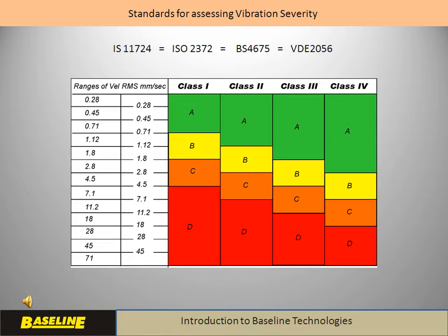It is also our experience that levels controlled to B levels or better actually result in significant reduction of breakdowns and bearing replacement costs. It must also be mentioned that in vibration, the normal range of accuracy is plus minus 10%. Since a lot of factors affect the vibrations, such accuracy levels are considered adequate internationally. The action points normally occur at a change of 50% or more in vibration levels at the same point on a given machine.